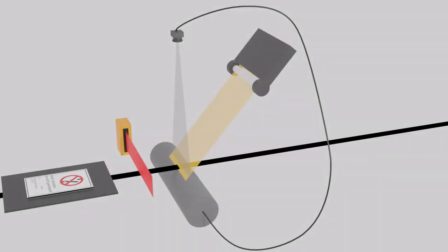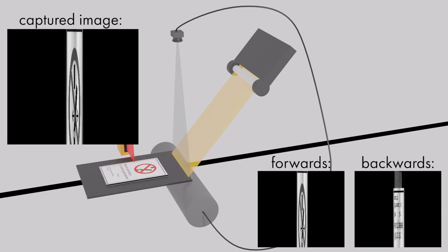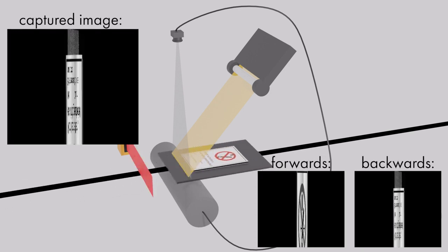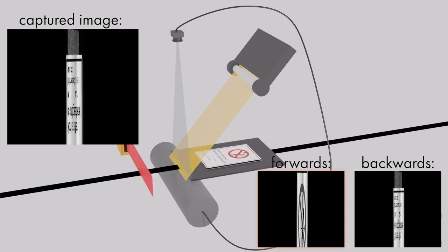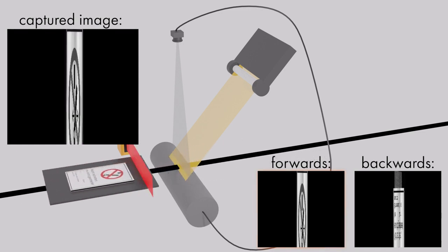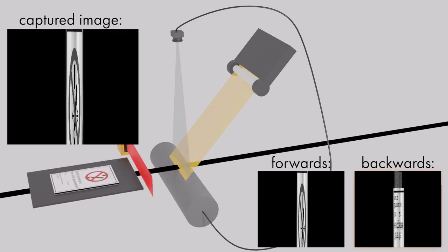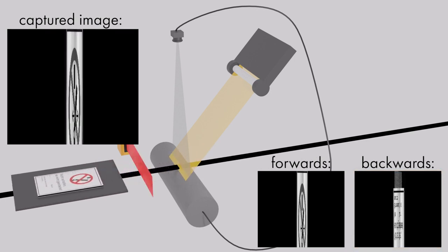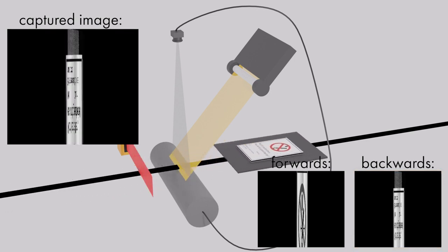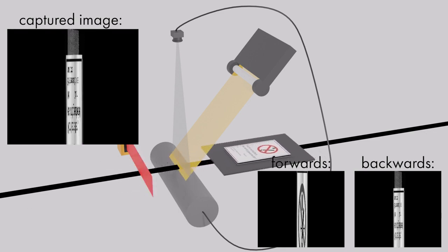Now let us run our setup with only the photoelectric sensor configured. As you can see, the camera is capturing images in both movement directions. In one direction, the images are capturing part of the sign with a wrong resolution in my direction. The images captured from the other direction also show only part of the sign, which is on top mirrored horizontally. So we want to synchronize the speed of the line acquisition and exclude the backwards movement from our image acquisition. For this, we use an encoder.